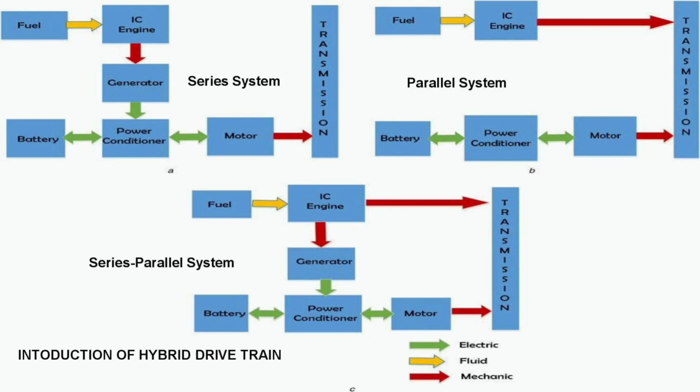Mode 2, during normal driving, the required traction power is supplied by the ICE only and the EM remains in off mode. Mode 3, during braking or deceleration, the EM acts as the generator to charge the battery through the power converter.